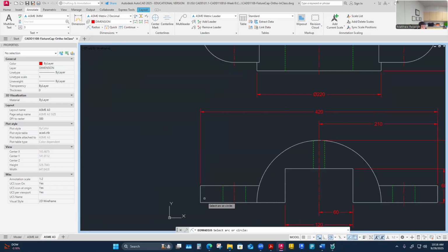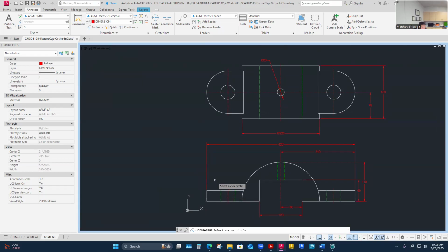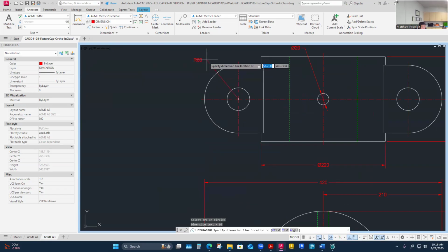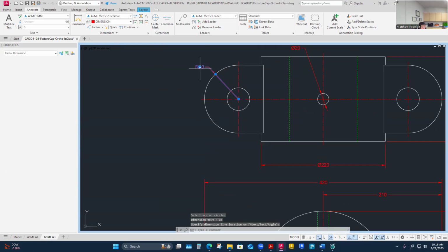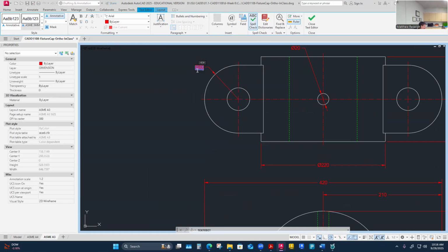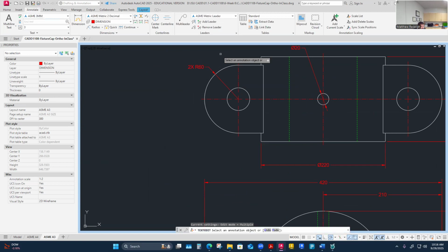It's not going to be great to dimension that down here in its rectangular view. Radiuses are generally used with a leader line like this. And there are two of these radiuses, so I am going to add this as a 2X, capital X, with a space only between the two. 2X of that radius. That's at least the radius of the ear size.